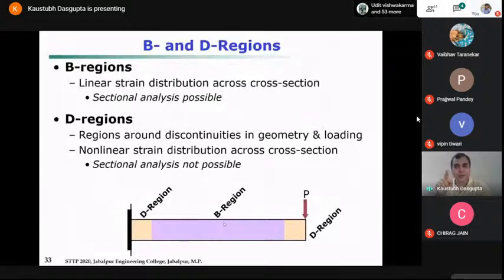Bending stress sigma equals My by I. So this is proportional to the bending moment, and along the depth of the section where you are evaluating the bending stress, that is determined by that small y, and you have the second moment of area as the denominator. Now that equation is applicable, with all those underlying assumptions, in a particular region of the beam.